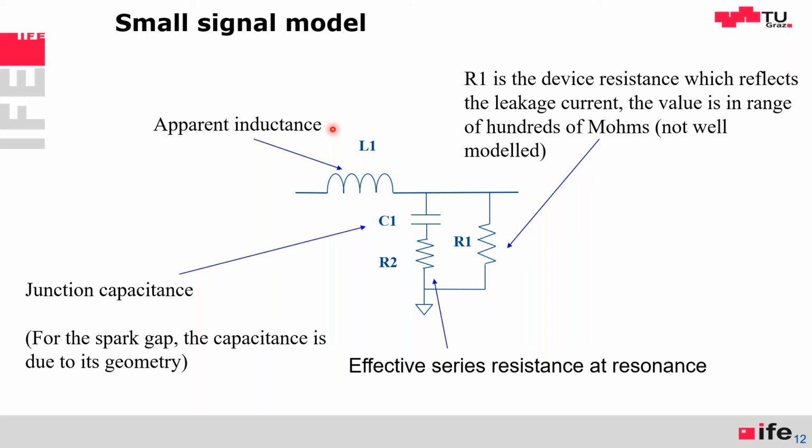But we always solder these capacitors in the same way on the PCBs. So the practical loops formed on most PCBs are similar. Then we can say the loop has this inductance, and we associate some part of the inductance to the capacitor. So this is not an inductance of the capacitor, that's an apparent or effective inductance. But we should always be reminded that you cannot assign inductance to a single component, only if you know the complete current path.